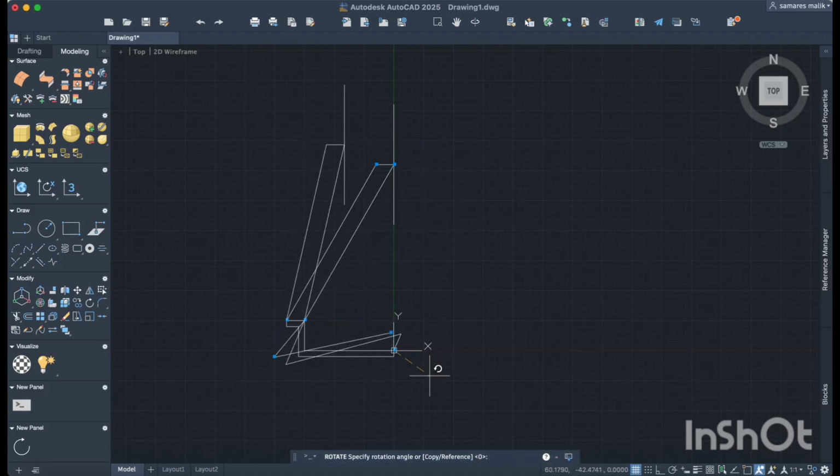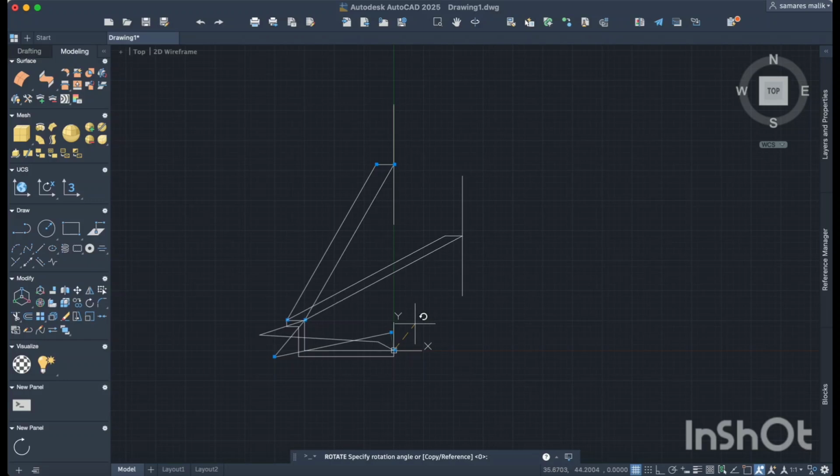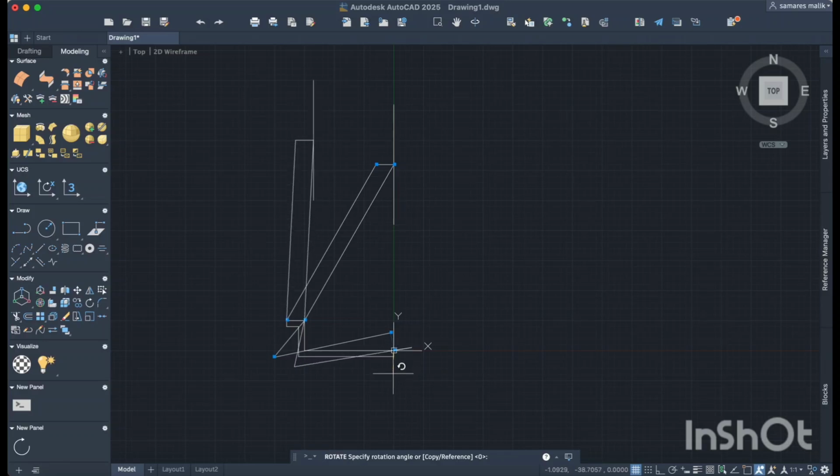As you can see, it is rotating and the wiper is moving to and fro, and we are getting a wipe area. We can improve upon this by changing the actuator link, and this will result in a larger wiper area. And let us stop it.